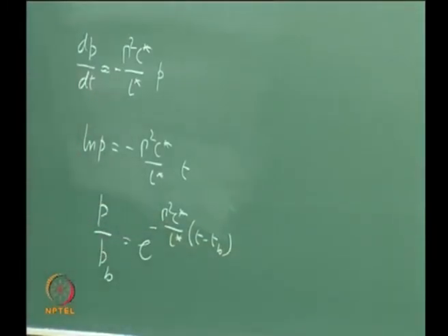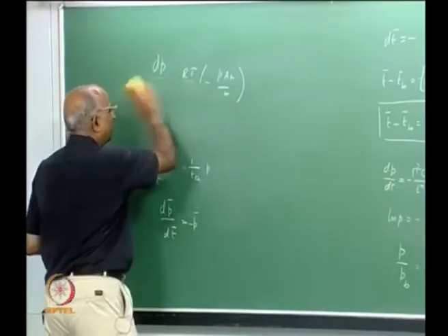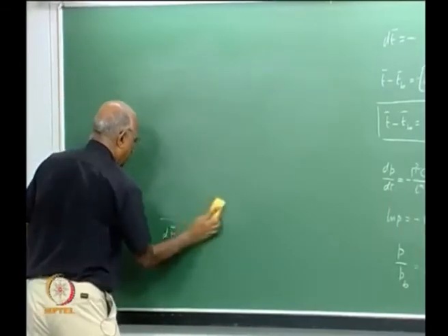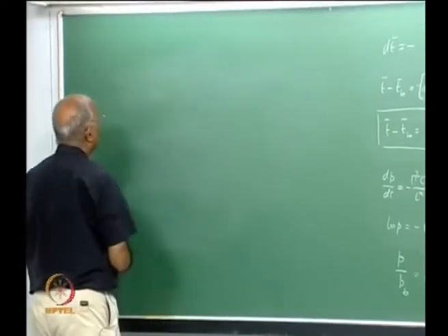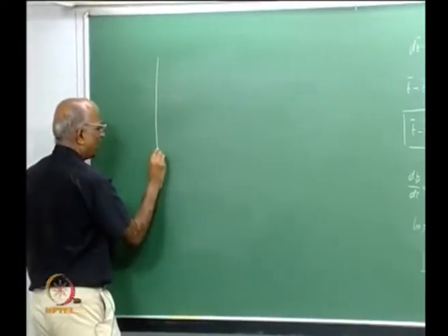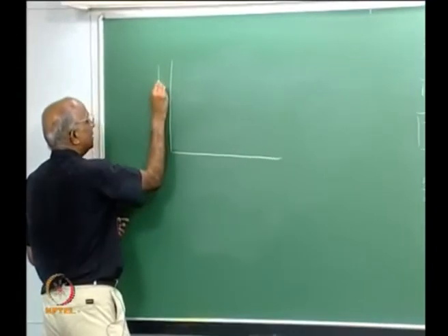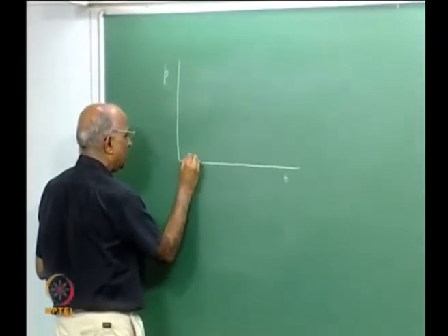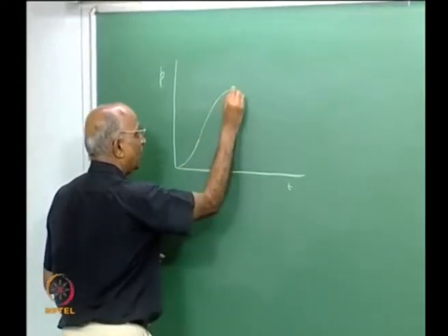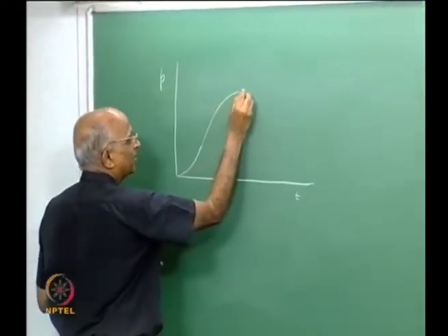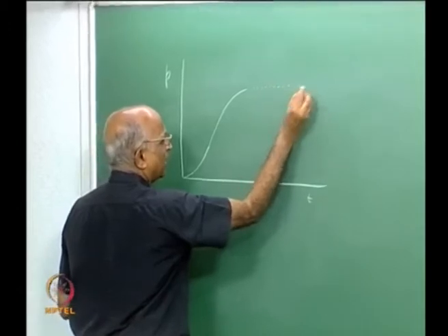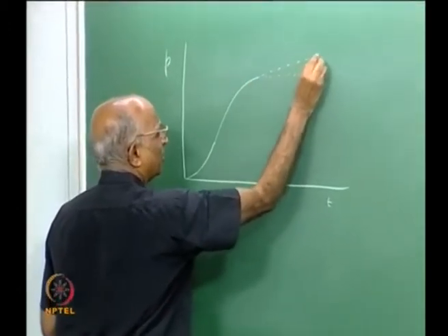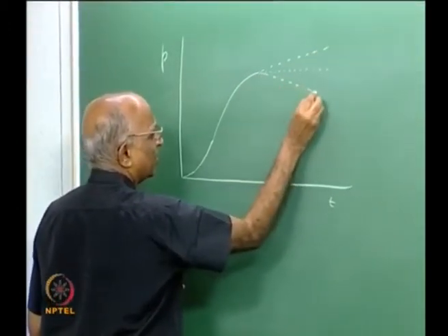Therefore, why are we doing all this? See, there must be some reason, right? The reason is, now what is it we have established? We say whenever a rocket motor ignites, the pressure changes with time, starts slowly, builds up, flame spread, goes over here, then reaches, if it is neutral it goes like this, if it is progressive it goes like this, if it is regressive it goes like this.